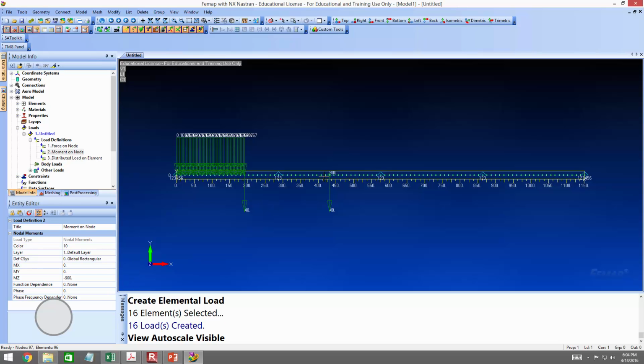Now, we're going to do this a little differently, okay? So everybody pay attention up here for a sec. I'm going to show you a method for doing this called data surfacing. And the benefit of using something like a data surface is that you can do fairly complicated analyses or fairly complicated load patterns really, really easily, okay?